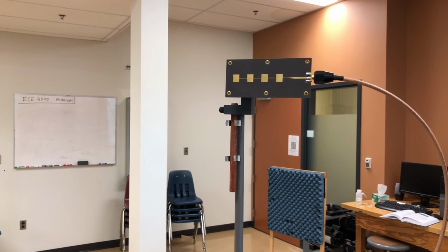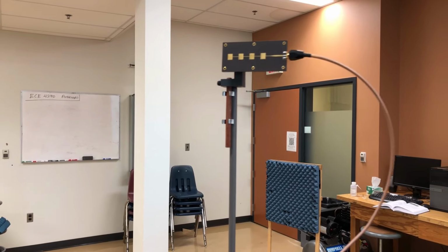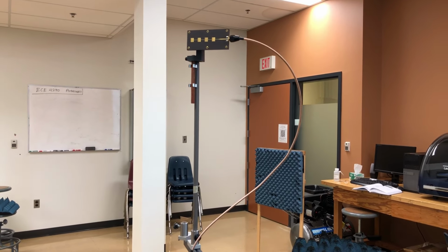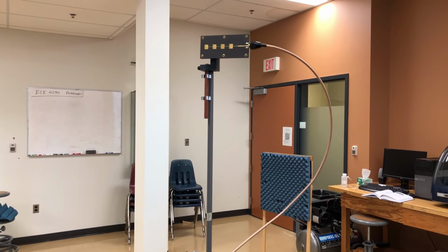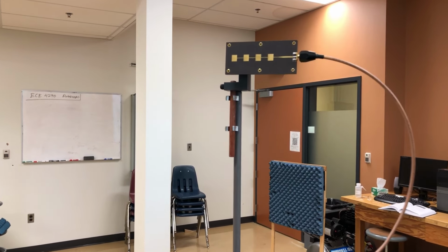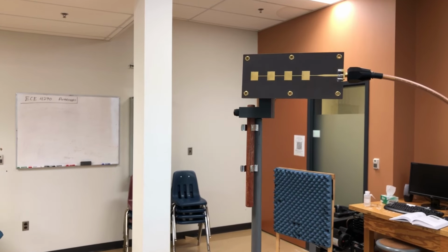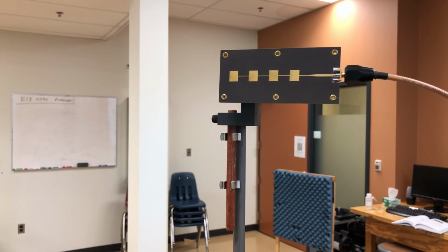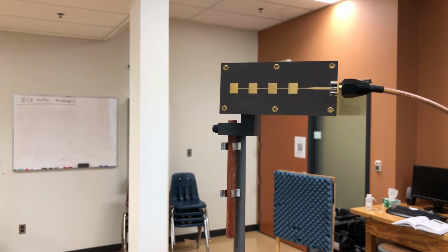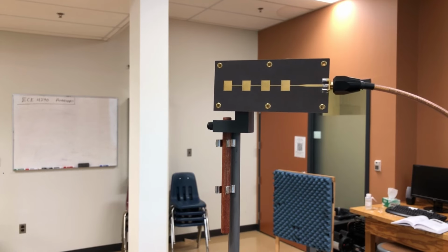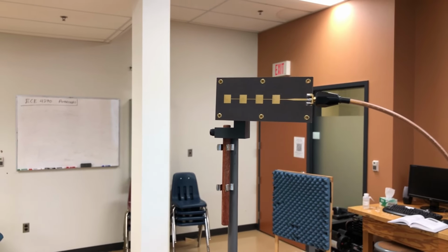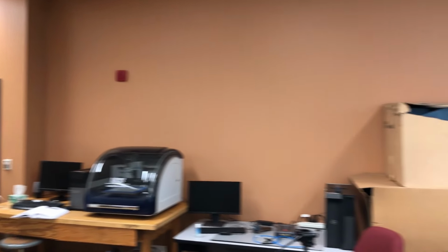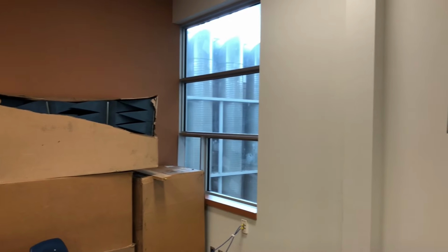So now if it rotates using this configuration, this is essentially E-plane. Just one thing to keep in mind here is that if you look at this patch array closely, you see that the polarization that this needs to receive is horizontal polarization. Look at the feed line, and then you can figure out that it expects horizontal polarization. Therefore, our horn antenna subsequently needs to be rotated by 90 degrees. I have done that already.